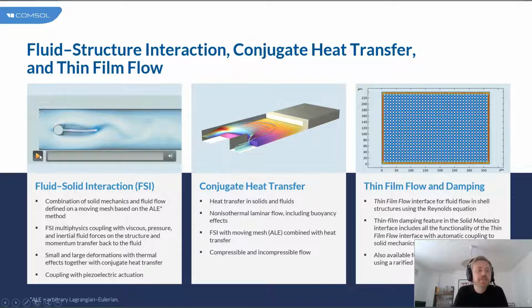You will also notice here that we're looking at a mesh which is moving. When working with fluid structure interaction, if we're dealing with large deformations, it's important for us to be able to model the flow around the deformed structure as opposed to the undeformed structure. And the way that we deal with that is by deforming the mesh so that we can update the shape of the structure during the simulation and model the deformed shape as opposed to the initial shape.